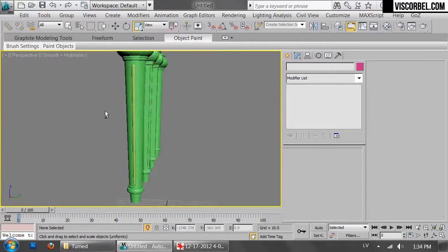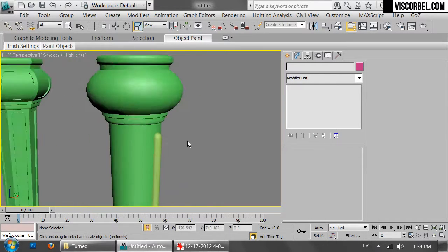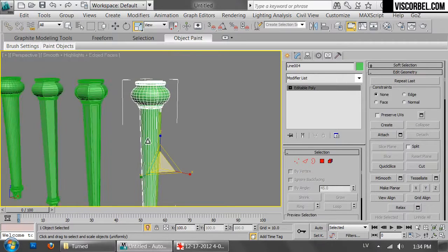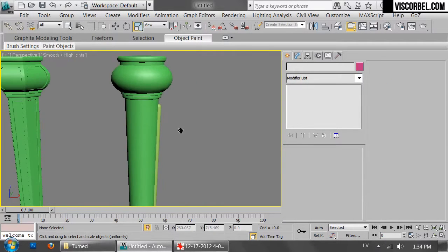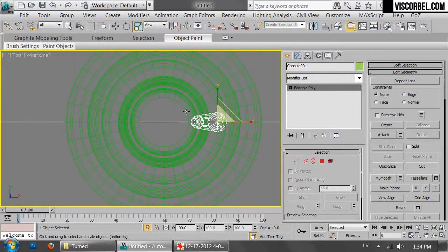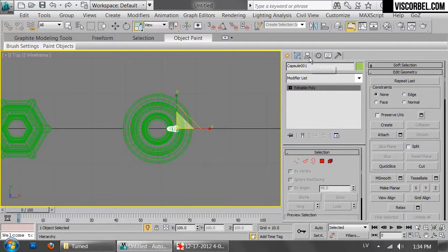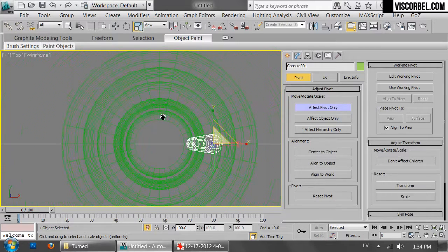And what we're going to do is we're going to use the Pro Boolean tool to just cut out the shape from our original leg. First, we need to make some copies. Again, that's easy to do. First thing you have to do is center your pivot point on the leg. So I'm just going to do it manually, or you can use the align tool for that as well.